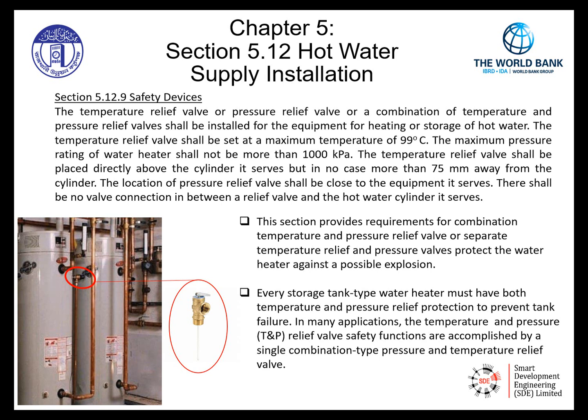As seen in the picture to the left, there is a hot water storage appliance with a temperature and pressure combination valve. Combination temperature and pressure relief valve as shown. And it is not more than 75 feet away from the cylinder and appears to comply with the code so far.